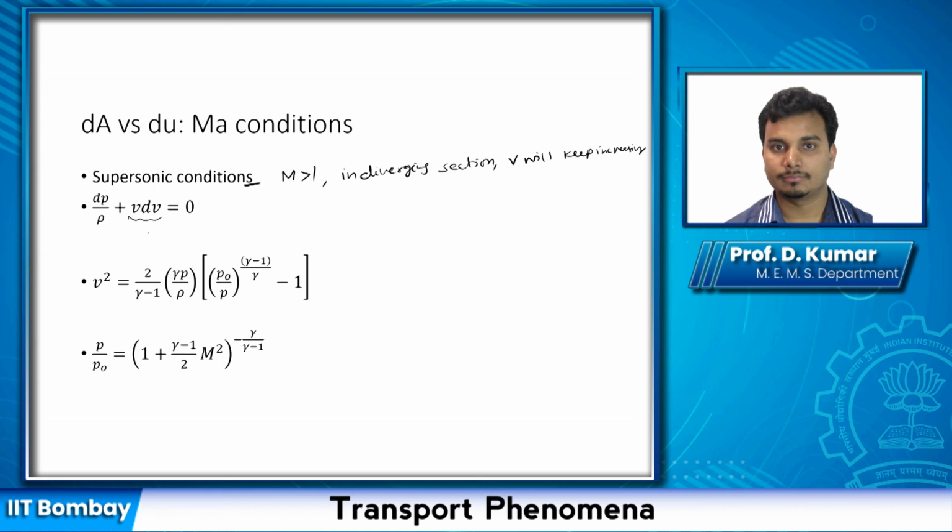For that, you can actually integrate this and come up with solutions. Integrating this part is simple, it's just V squared by 2. Since this nozzle is small, we can consider this as adiabatic, and we have seen how to integrate if it is adiabatic. You don't have to do it from 1 to 2, it can be 1 to any point x, so P naught to P. And since we already know that P rho to the minus gamma is constant, from here you can integrate this.